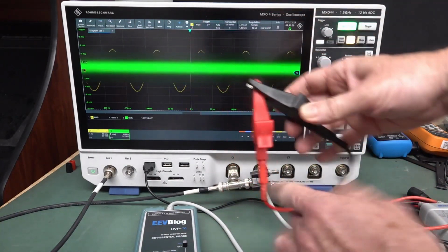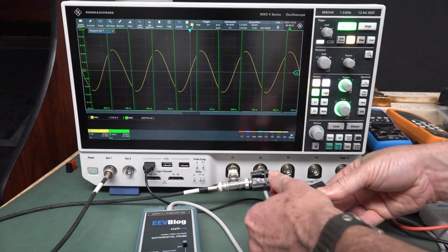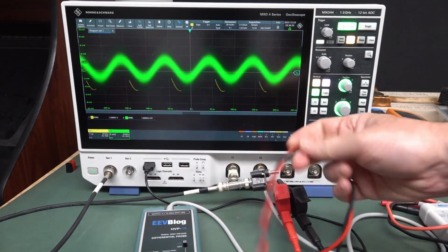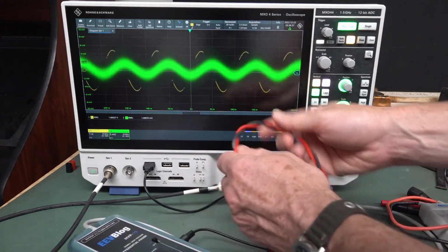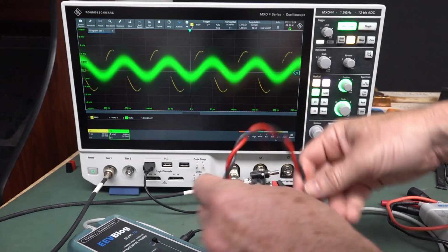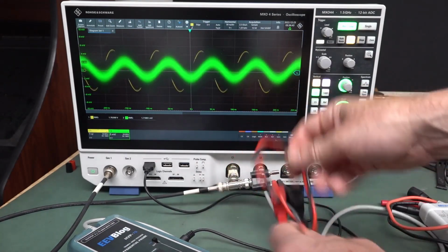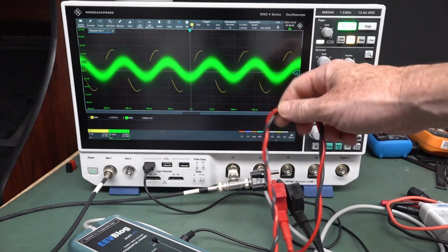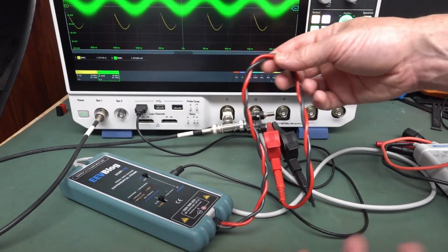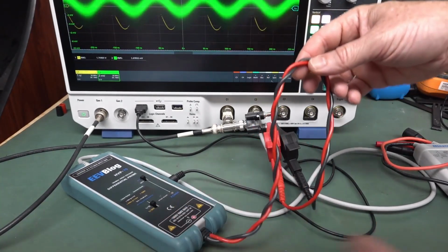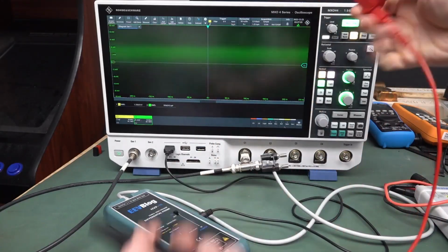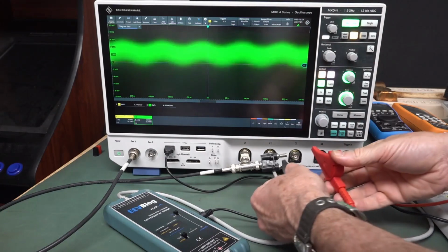And it doesn't matter what I do to the probes here, but this one, if we hook it back up, you'll notice that if I start playing with those probes, things start happening, okay? It starts being influenced because we've got these long leads here. That's why a differential probe with really short leads is better, but most probes have them built in, unfortunately. So what happens if I untwist those leads like this?